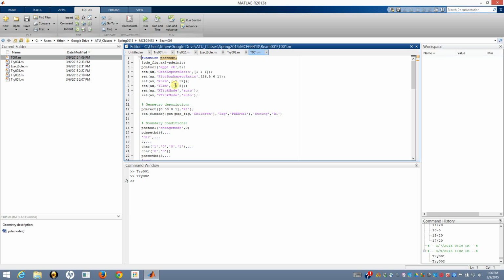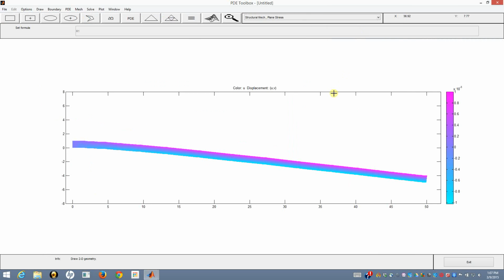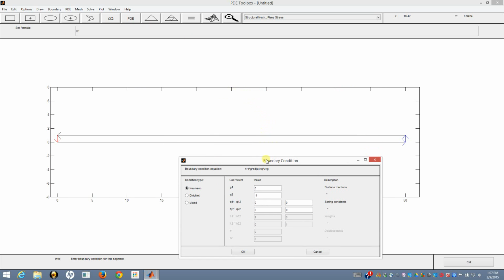And instead of it being -4 and 8, I'll say -8 and 8. That'll make the bottom of the box a little bigger. So does that seem like it makes sense? I mean, what I'm doing here across the top of the beam is putting a load of 1, but that's based upon the concept that the thickness that we had before was 0.001.